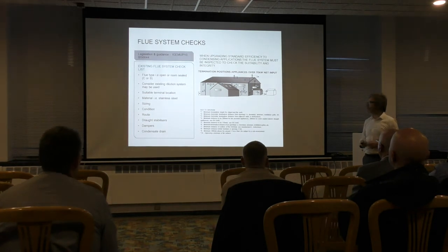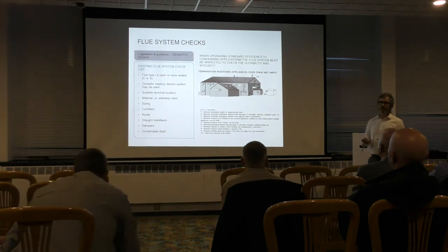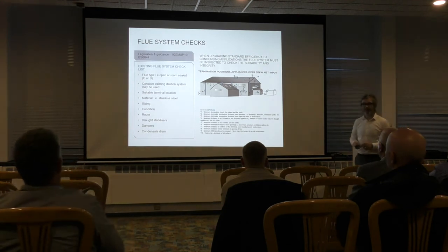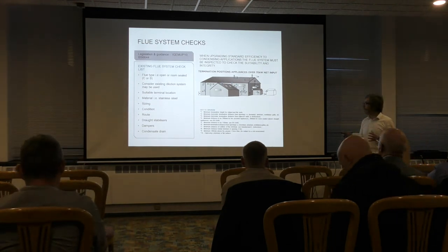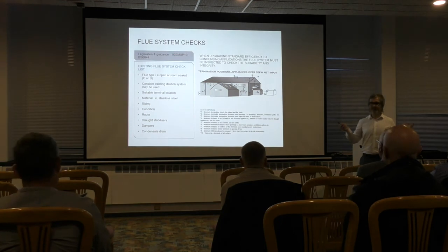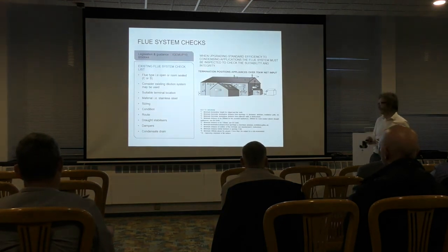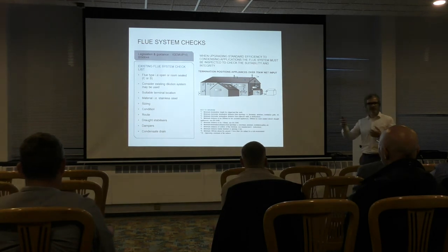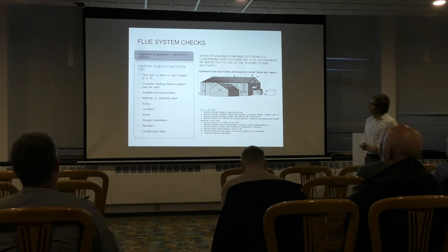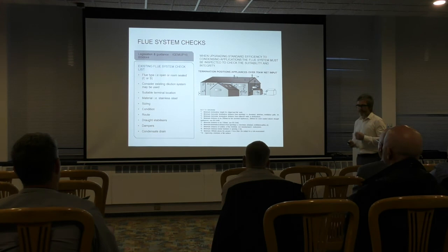But what it can do is create a nuisance. So what I would say is, put the boilers on the flue dilution system, but just be aware of what's around the building, because you don't want to start annoying the neighbours, or have them start complaining: this time last week we didn't have this amount of pluming, and now we've got all this pluming coming out. Suitable terminal location.